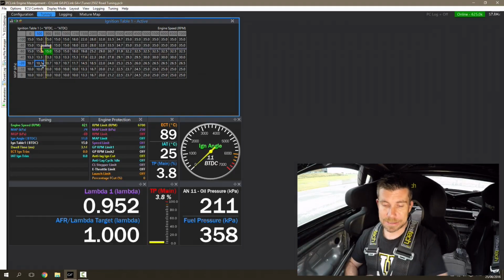Now the way I do this comes from years of experience tuning engines on a dyno and seeing what different types of engines want to see in the way of ignition timing, as well as analysing factory OE ignition timing maps. And I've provided base timing maps that should be a good starting point for both naturally aspirated and turbocharged engines in this course for you to get up and running. Let's have a look at the ignition timing that we've put into our VQ35 here as an example.